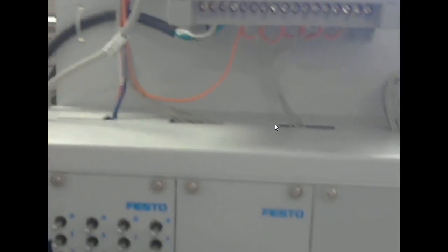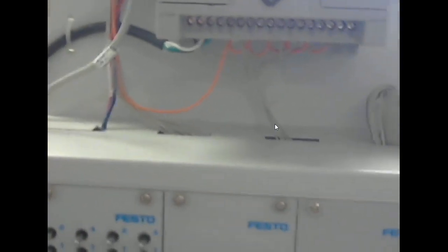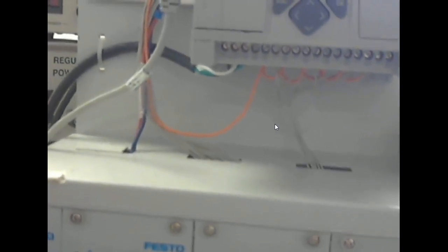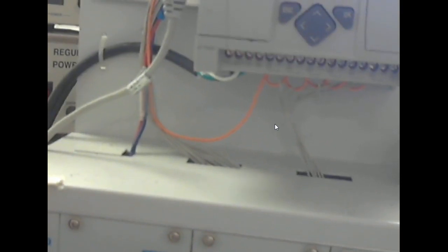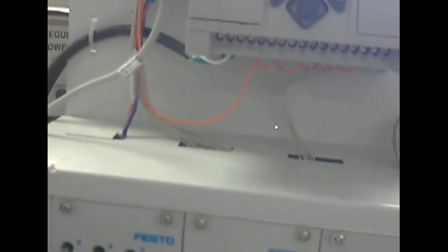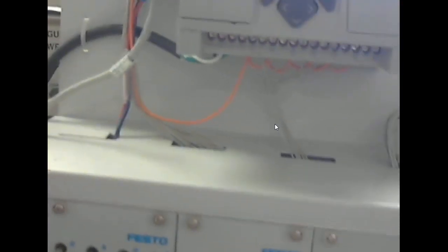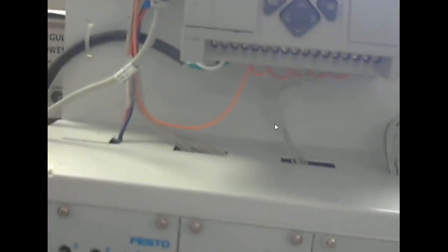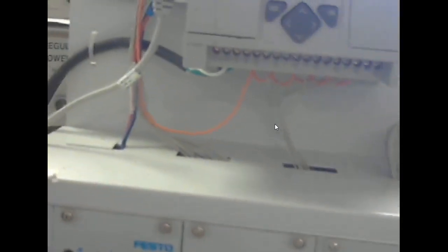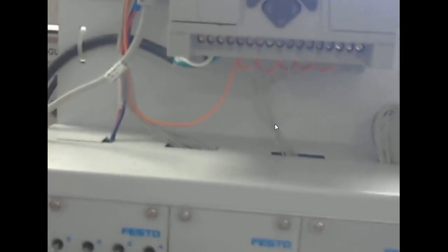Well, switches are rated in two things. If you ever went out and bought a light switch, it's usually rated at something like 15 amps, and then it's rated at the amount of voltage that it can block, right? When a switch breaks, it's trying to break a push, and if it arcs too much, it'll arc over. So switches and fuses are rated not only in the current they can handle, but also the voltage, the push, they can guarantee they can break.